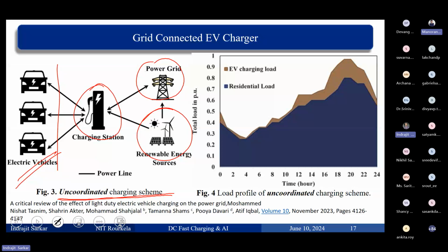And when it is an entire, huge grid, that means the inertia of the grid is huge. What is inertia? It means you have a big rock, and when you push it, the change in the state of the rock is not significant. Here also, when the grid is huge, the inertia of the grid is huge, so taking this amount of power from the grid is not going to affect the grid frequency.